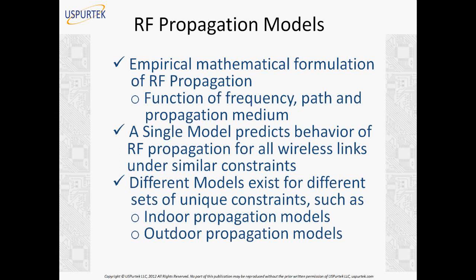We really have to go out in the field and do some drive tests, collect some data to understand the behavior of RF propagation. And then put these large collections of data into some empirical mathematical form. And those mathematical forms can be used for our future analysis for similar situations in the future. So that is why different models will exist for different sets of unique constraints, such as indoor or outdoor.